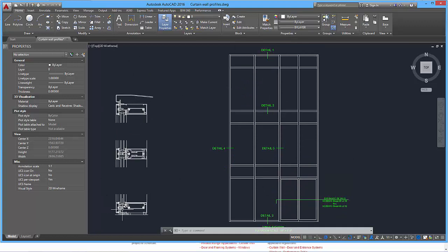Now one thing I've noticed is that the curtain system that I've put in the BIM model is back to front. So the glazing goes on the outside of this little cap, and then the business end sort of goes toward the inside of the building. So one of the things that we'll be doing in our Revit model is flipping the curtain wall system so it faces the correct way.